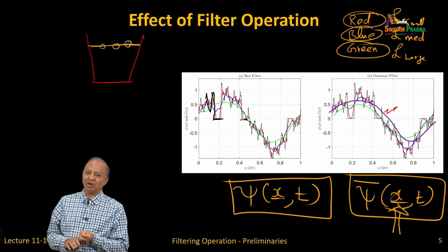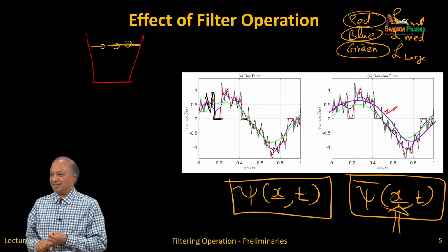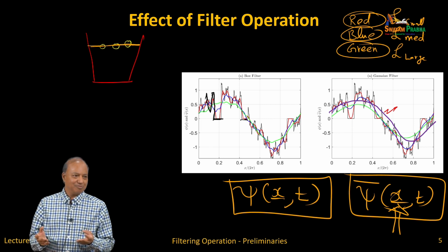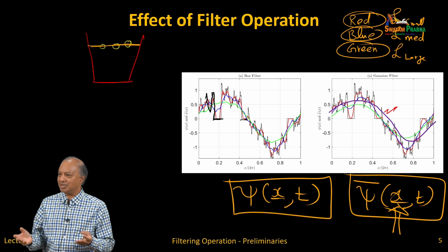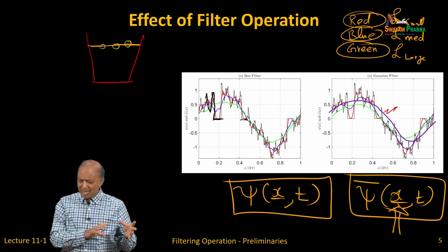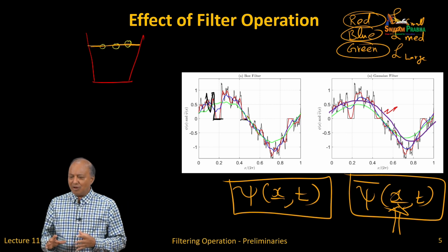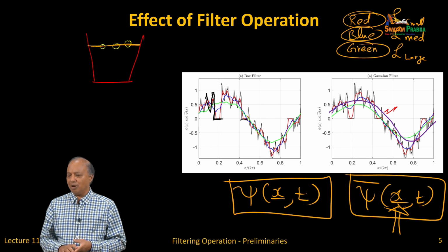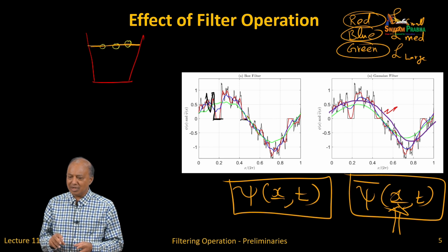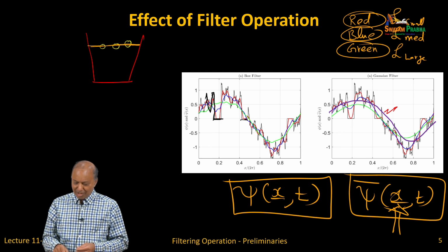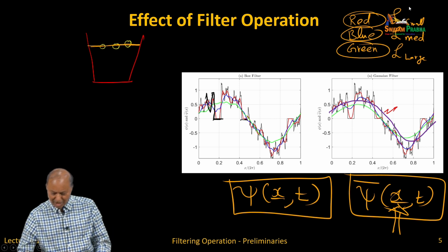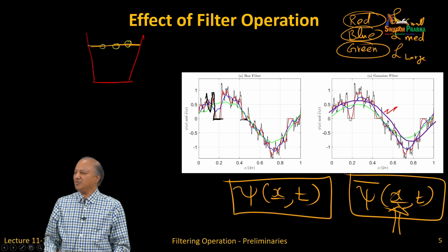And of course, when you do ensemble average, it doesn't make a whole lot of sense to do Lagrangian simulation. I don't know, does anyone do RANS simulations with Lagrangian particles? It makes much more sense to do Euler-Euler RANS simulation. So it makes the problem much simpler. But the downside is that in LES, we only have to model the subgrid portion. So in other words, if you were to choose a very fine filter width and choose the red curve, what you need to model is far less.